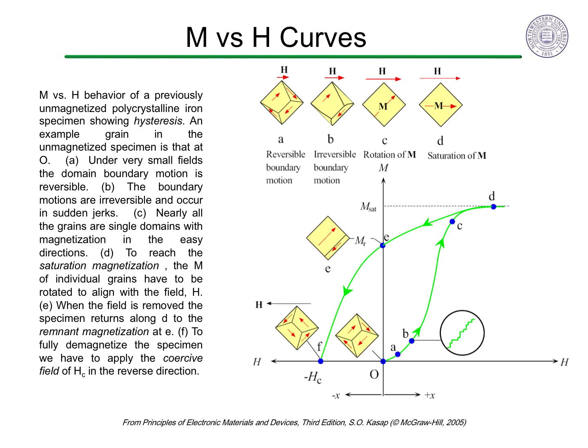As the magnetic field is reversed, the magnetization first rotates back to the easy direction, then some opposing domains may form due to the demagnetizing effects of the specimen. Some magnetization will remain even in zero applied field. This is called the remnant magnetization. Applying a magnetic field in the reverse direction will be needed to reduce the magnetization to zero.